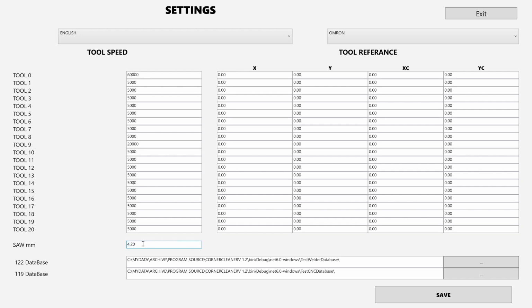You need to update the program step by step, because the program saves only positions. It doesn't know the bottom and top of the saw blade, only follows a line. So if you change to another saw blade with another thickness, keep in mind that the only thing that will change is the programming page. The program in the machine will not change.